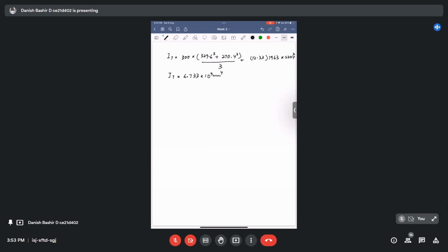So now here we will calculate the exact cracking moment, Mcr. I already told the formula: fcr times I transformed divided by yt.